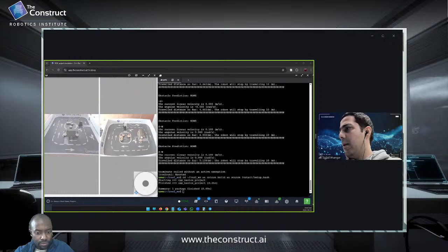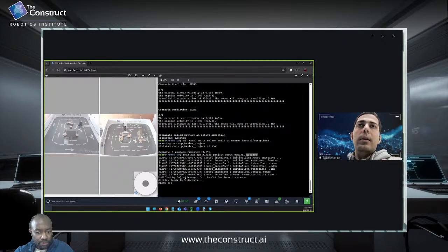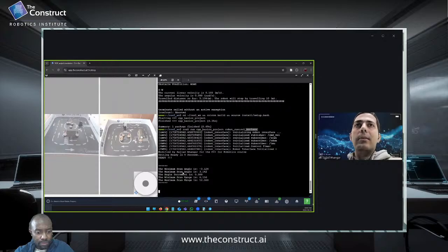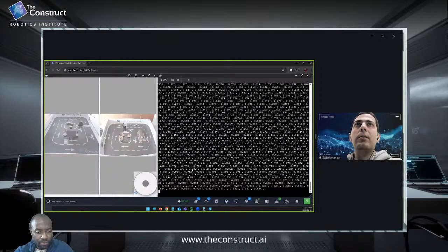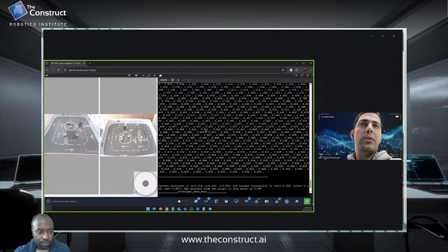So I update my terminal with this code, which is the no class version, and you can see that all the functions that were asked for appear. This is the maximum angle, minimum angle, and this is the scan range that the LiDAR scan returns. There is no infinity at the moment. Oh yeah, there is someone here, which we handled in other functions. This is the current position, current orientation, and the distance from the origin.